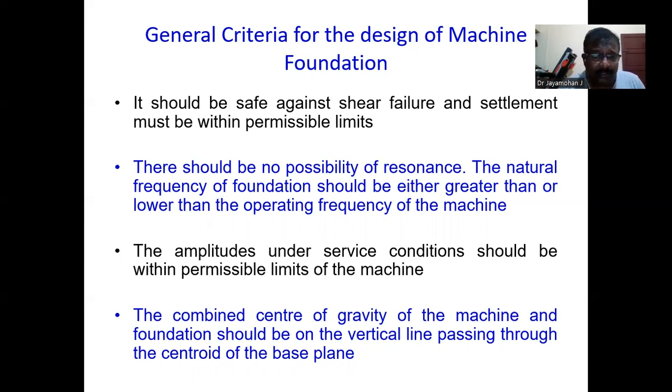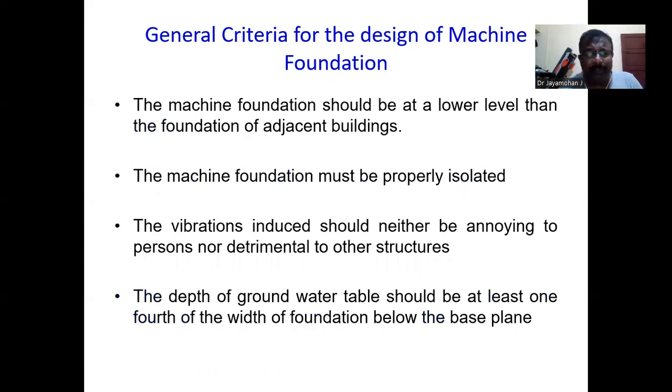So the amplitudes under service conditions should be within permissible limits of the machine. And more importantly, the center of gravity of the machine and the center of gravity of the foundation must lie on the same vertical line, so as to prevent differential settlement. That is a very important aspect.